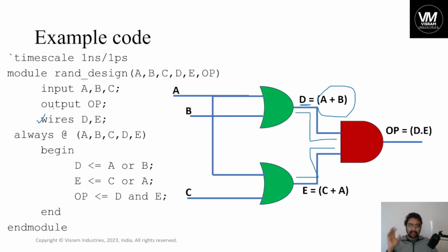Now let us understand what we are achieving from HDL language. We are achieving logic connection cells in the physical environment, on the FPGA hardware you require. So we are achieving hardware based on the Verilog HDL text code. So: module random_design. You can name this as you like, but it has syntax sensitivity. You need to write all the lowercase letters and underscore in it, and you need to declare input, output.